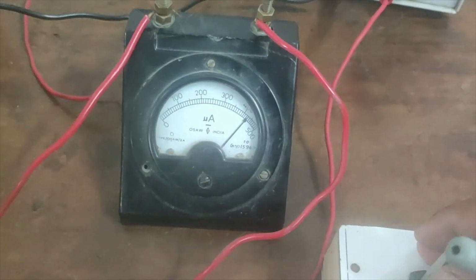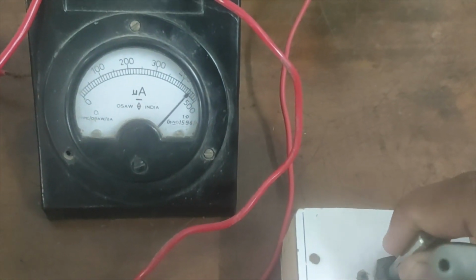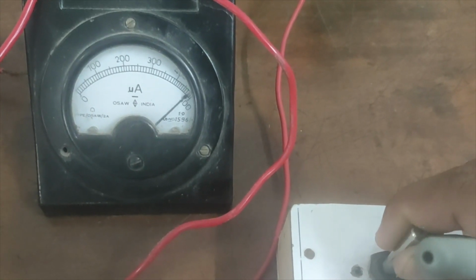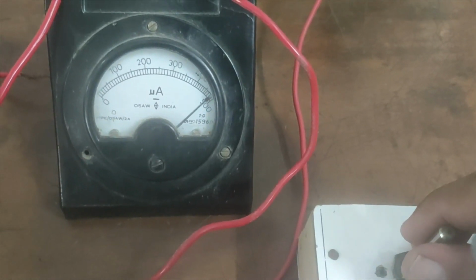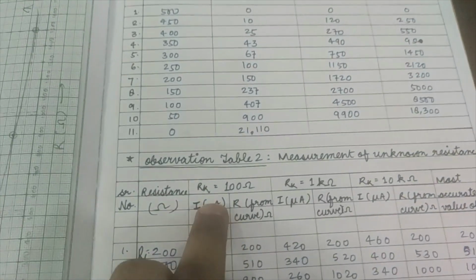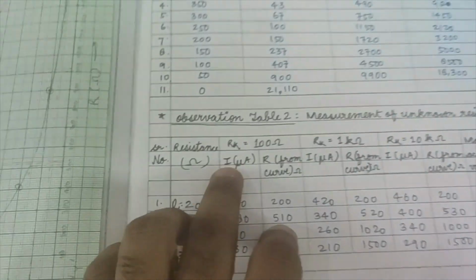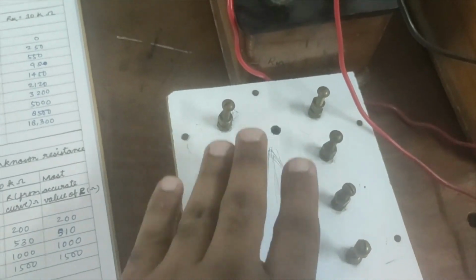So this is 0, and if you switch on the circuit, you have the deflection here, and then make a full deflection using the potentiometer. Make the full deflection carefully. So with RK at 100 ohm and RV still 0, with no resistance here, we made the full scale deflection. Now, in place of this, we have to introduce these 4 resistances.